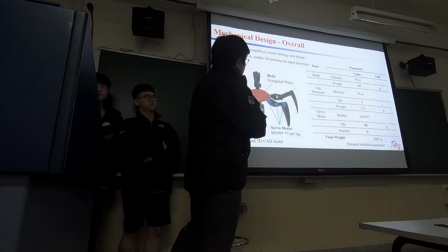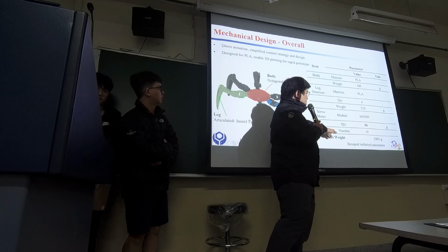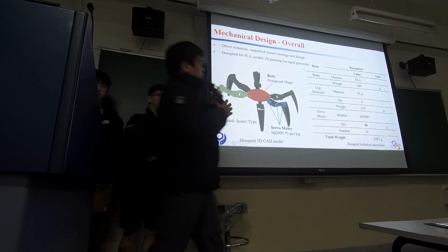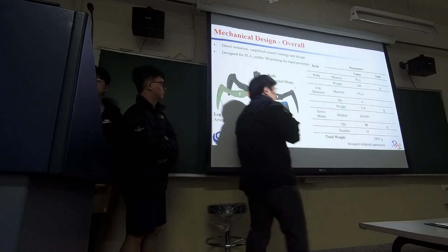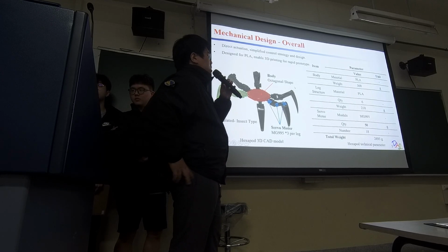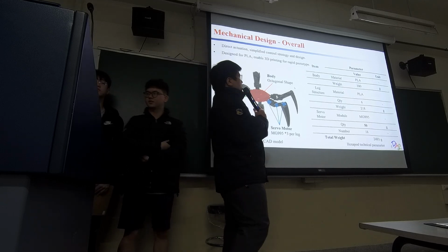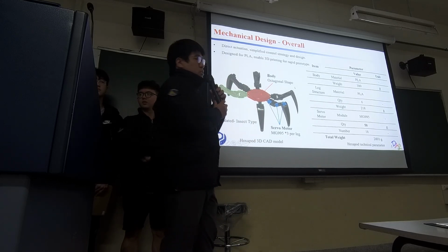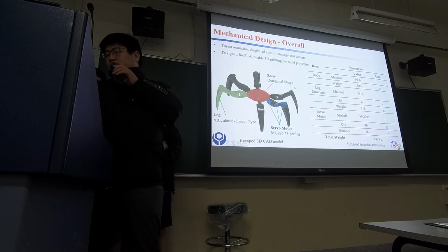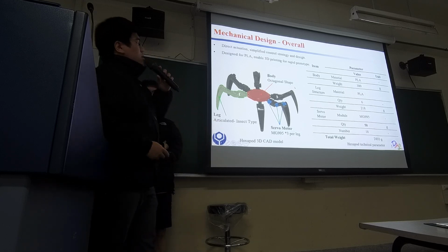We totally have 18 servo motors. Every one of them is 50 gram weight, and the leg structure itself is 218 gram, and the body itself is 300 gram. All of them were considered to be of PLA material to simulate the 3D printing prototypes.